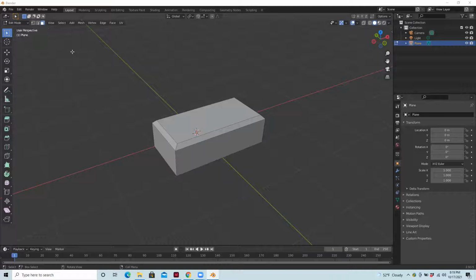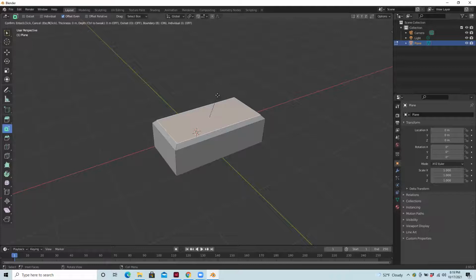I'm going to go ahead and select face again, the top face. And then there is a tool called Inset Faces. So you go ahead and click on that. And then this time when I drag the handle, kind of up or down, you can see what's actually happening is it's created a new face. It's almost like it duplicated the face I had selected. And then I can drag to inset it.